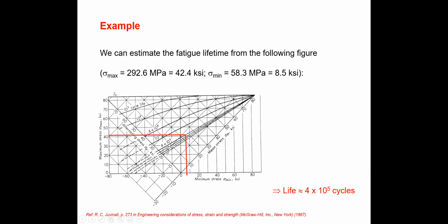So draw the lines and find the crossing point. So you can get the fatigue lifetime. You can see this line goes through this point. So that is the fatigue lifetime. So in this particular loading pattern, that element has 4 times 10 to the power 5 cycles of fatigue lifetime.